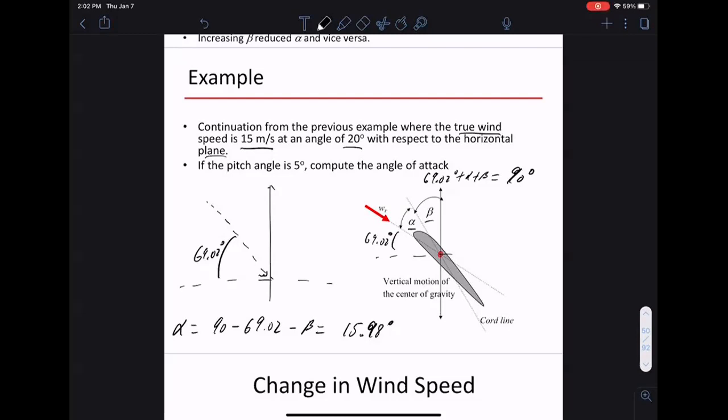So you don't want to go through the force calculation, then torque, then power. You want to summarize this whole thing in one number. I measure upstream wind speed, I know the upstream wind power density, and I can just multiply by one number to get the amount of electric power I can generate. That's what we will do next. That number will capture everything we talked about here. The reason we talk about pitch and forces is that, as you'll see later, this coefficient of performance also depends on pitch.